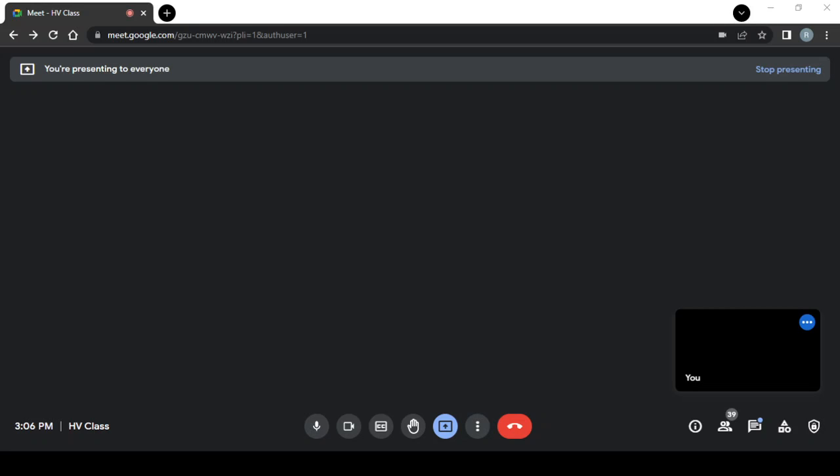And advantages and disadvantages. For this one, no loading, no direct connection to the HV electrode. Okay, because this one is driven by a capacitor, by electrostatic voltage, so they are not connected to the HV electrode, it can be isolated. The scale is linear. Linear means you increase 10 volts, the current will increase 1 amp or 1 milliamp.